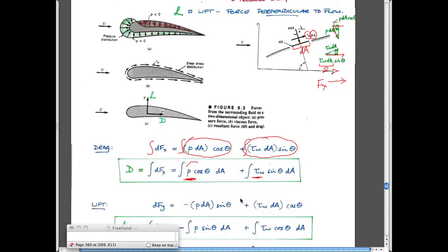And so that's really where that comes from. If you look at an airfoil, you can decompose it down into those two components as well, right? You have an air velocity coming in, it hits the airfoil at a stagnation point, and the flow then has to go around. So you'd expect the pressure here to be large, because the velocity is going from U to 0 at this point. So that magnitude, delta P over gamma, should be about equal to what? A half V squared over g, right? Just because of that. And as you went around here, it would diminish.